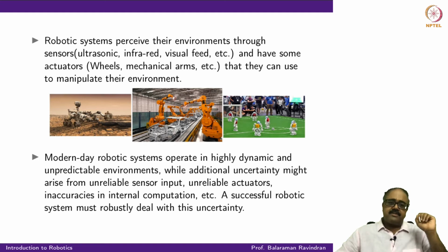One of these reasons is that the sensory information is not complete. So for example, say I'm using ultrasound sensors, let's say I have 8 ultrasound sensors pointing in 8 different directions. In each of those directions, the ultrasound sensor is going to tell me where my nearest obstacle is. But that is usually not enough for me to localize myself within a room. I don't know exactly where I am just because I have this sensory information coming in. So the sensory information is incomplete and therefore unreliable in that way.